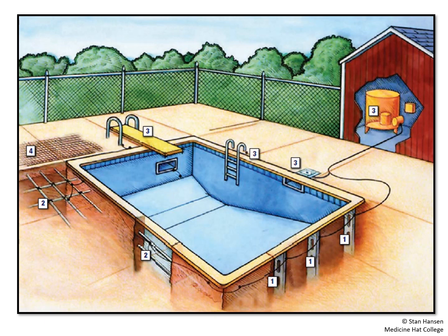Any buildings that are within 1.5 meters of the pool that have any exposed metal like siding or downspouts also must be bonded, and we cannot overlook those. If we have a continuous metal pool made of separate panels, each one of those separate panels needs to be securely connected together either with bolts or by welding, and they must be bonded at least one location.